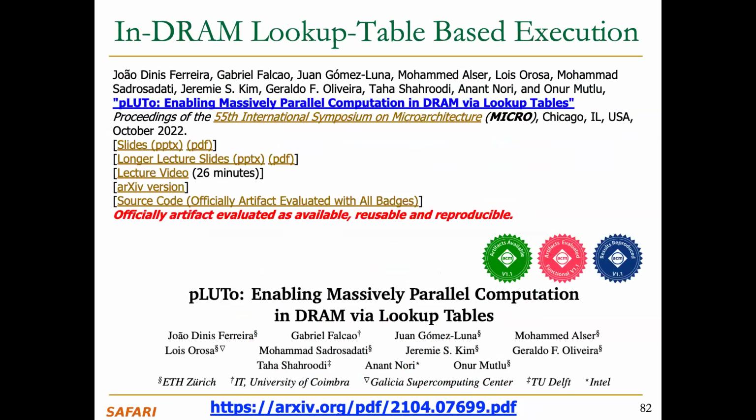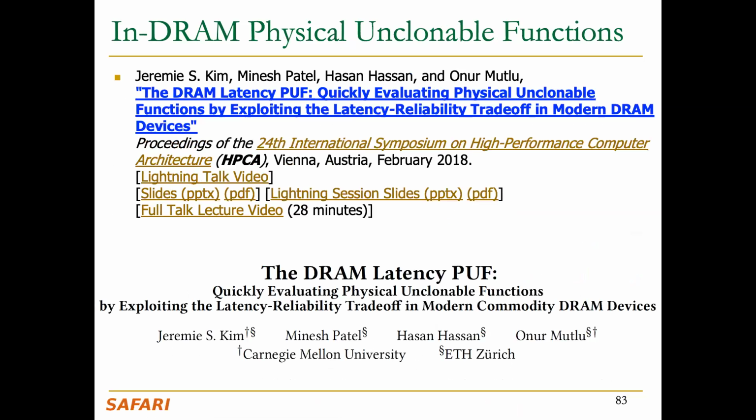Now, let me talk about what else you can do. So these are relatively simple bit serial operations, right? Of course, you can build multiplication, etc., like we discussed on top of those. But some operations are actually very expensive. For example, averaging or square root. And these are not easy to implement using these substrates. So we have a substrate that can do lookup table-based computation. If you have taken a logic course, you've probably seen logic using computation using lookup tables, right? Essentially, we can do the same thing in memory. I will not talk about that, but you can read the papers.